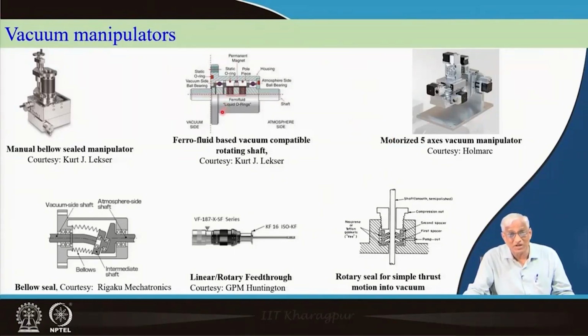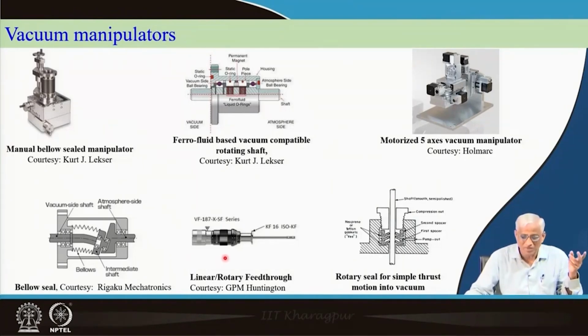You cannot use any material you want. These are not only mechanical devices, they are mechanical devices suitable for vacuum technology. So, surface finish is very important in those portions. For example, on the vacuum side surface finish is required, on this side it is not. So, it is a highly sophisticated material, that is the reason they are costly. But I would suggest some startups to come up, you can easily make these things. You are not making high quality chambers or high quality pumps, but you can make your own inexpensive, innovative manipulators, then you will have a very good market for it.